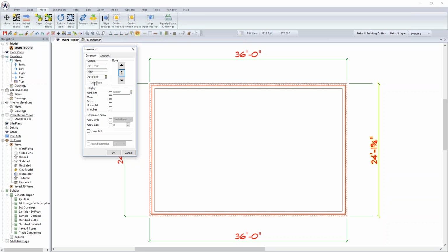And so you could have a basement, let's say, or a crawl space. You'll have a main floor plan and a second floor plan. If all three of those drawings were stacked in the model, you will have the ability to link the floors so that when you make a change on one of the three plans, all three plans are updated with the exact same change. It's a huge time saver, and it eliminates an error being made whereby you make the change on one drawing and don't make the same change on another drawing. This keeps consistency throughout the drawing. Okay, so that's a really big one that you'll want to know.